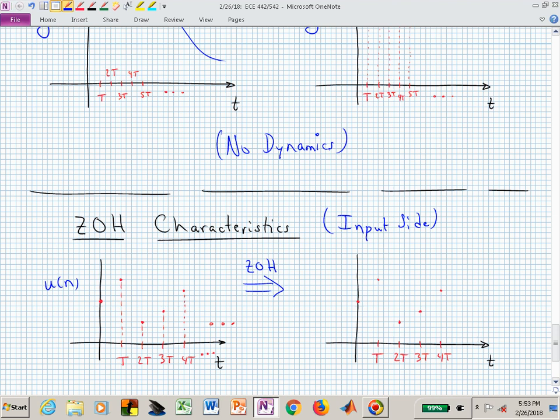A first order might be to draw a slope between where I am and where I'm going. Zero order just means assume that you're constant. So a zero order hold would say, when I go from digital to analog, what I want to do is, when I start at time 0, I'm just going to hold that value until I get the next update, which is at time step capital T. There I'm going to jump up to this next value and hold that constant until I get to the next value, which really says that I could think of this as piecewise constant.